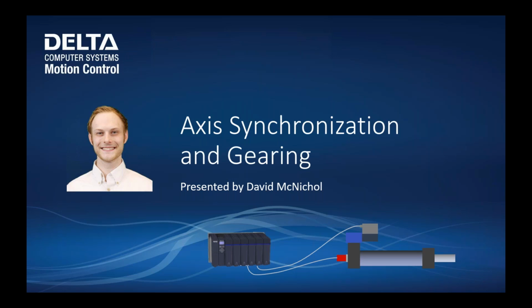Today's topic is going to be axis synchronization and gearing. Now, if you're familiar with Delta, you'll already know that we have a few gearing commands, but we're going to go a little bit more in depth today. We're going to talk about not only our gearing commands, but really just synchronization in general, how to get things set up quickly, and some best practices as you're trying to gear together or synchronize and cam different axes.